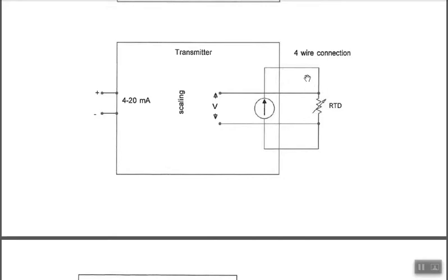It doesn't mean you have to use them. So you can have a 4-wire RTD and use it with a 2-wire connection. Not a big deal, right? You just have 2 wires that you're not going to use. So just use one of the white wires. You wouldn't use this wire. This would not be used. And you wouldn't use this red wire. So a 4-wire RTD is universal. You can use it as a 4-wire or a 2-wire.